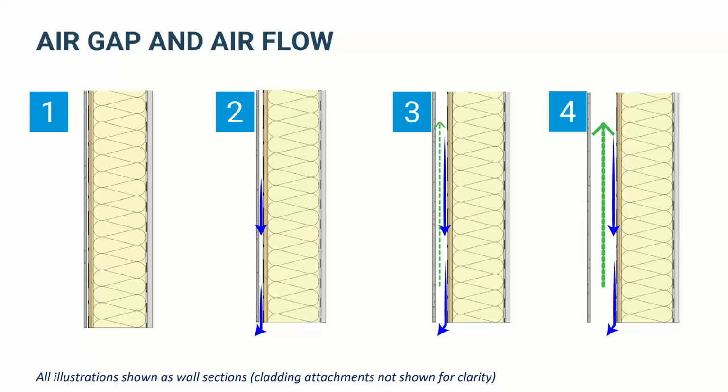I will say that you don't actually need a 1/2 inch to drain effectively, but you see these larger gaps really for a couple of reasons. Number one is a lot of the materials that we use to create these gaps are either a 1/2 inch or 3/4 inch or 1 inch. So you're just going to create that cavity by the geometry of the materials you're using, whether that's furring strips or a drain mat or something like that. You're not going to get it super thin.